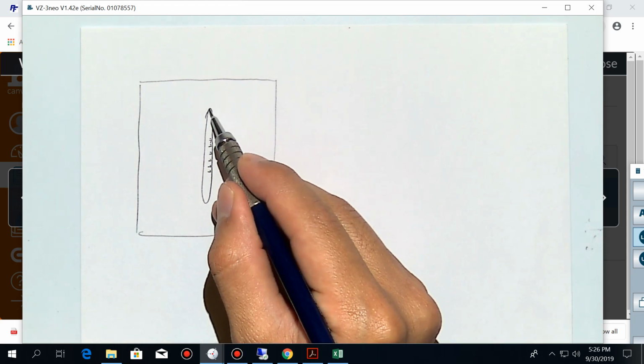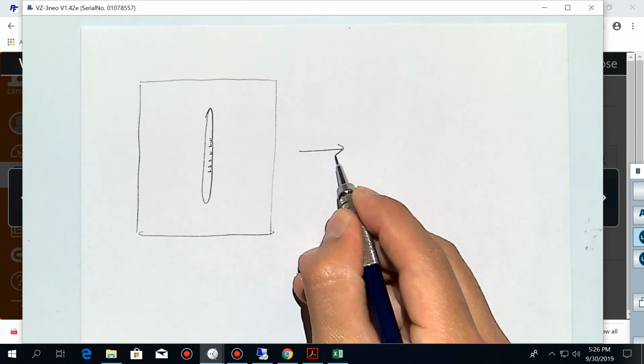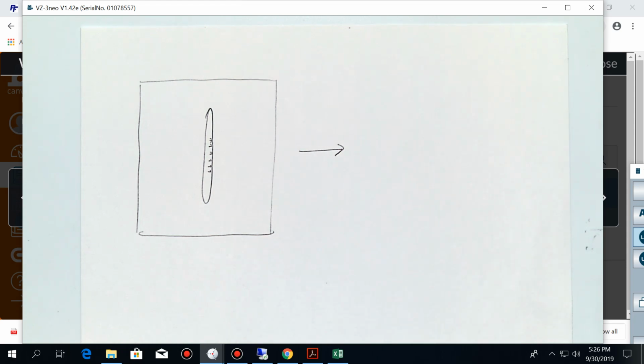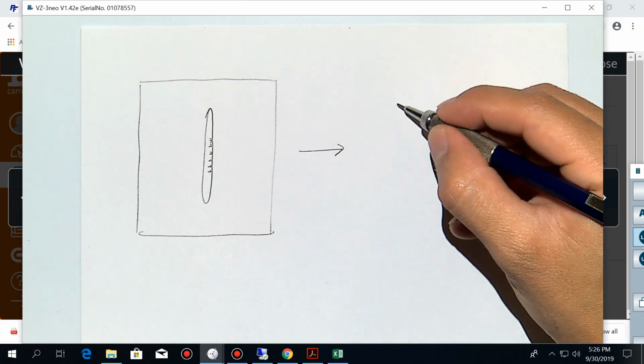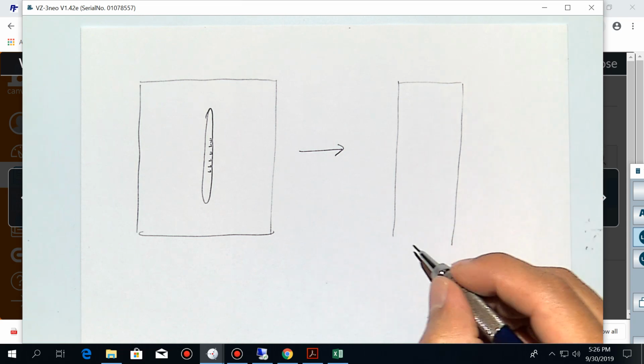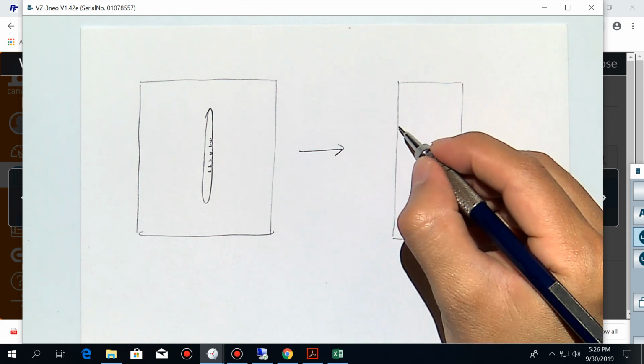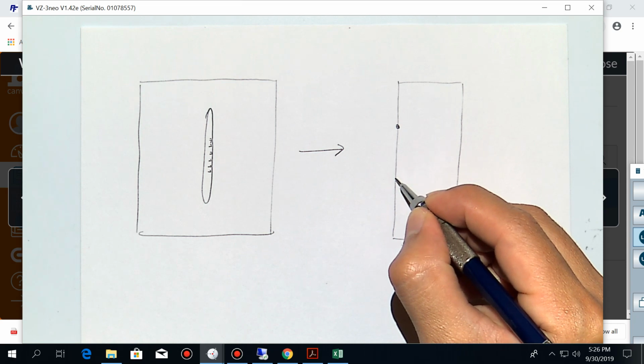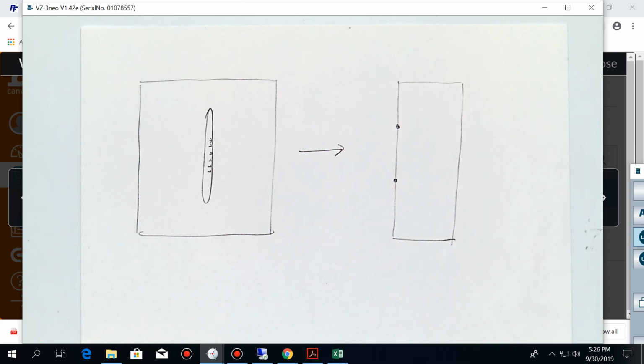But that created some problems because the closer you get to the tips of the fracture, you may get some errors of convergence and the mesh may not be enough. So with the new version, the online version, I'm asking you to simulate just half of the domain in which the fracture is just going to be a line when you start.